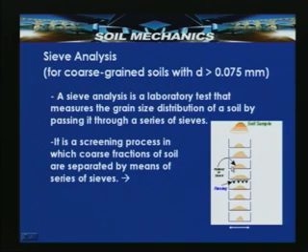Here you can see this particular portion of the soil which has passed through these two sieves and been collected here, and this is the portion of the soil which is passing through this particular sieve above. This indicates that the particles passing through this sieve are finer than the sieve sizes lying above. So, with this method we segregate the soil into different compositions of equivalent diameter of the particles to determine the grain size distribution.